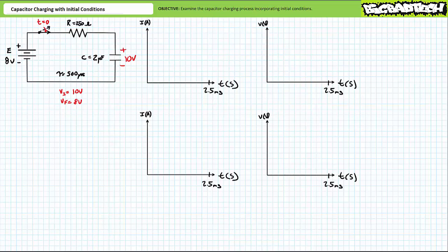My first question to you is this. What happens during this quote-unquote charge phase when the switch closes at time t equals 0? Here's a hint. Consider instrumentation placed in the following fashion. Voltmeter C reads the voltage across the capacitor, positive to negative, top to bottom. Ammeter C reads the current through the capacitor, in to out, top to bottom.